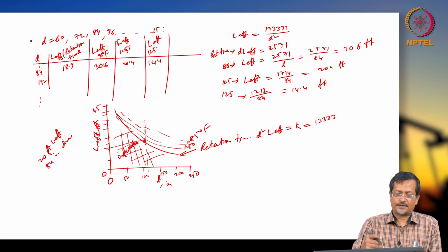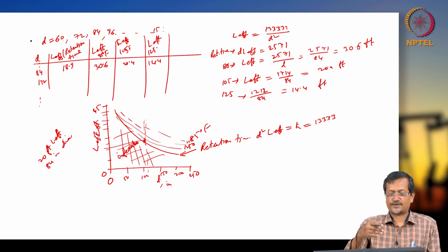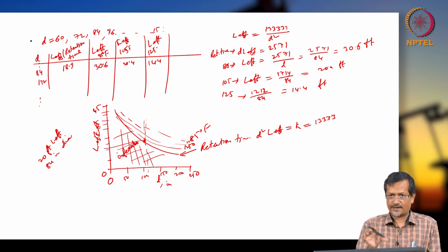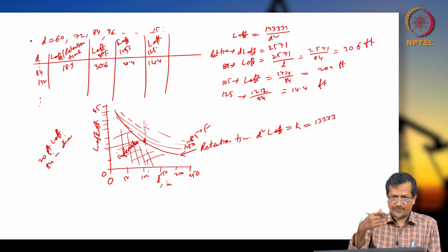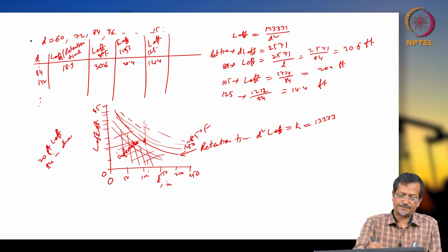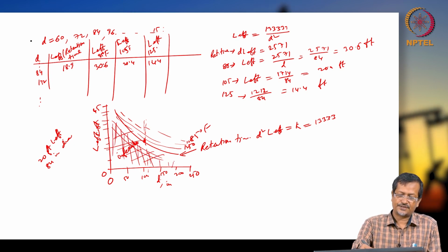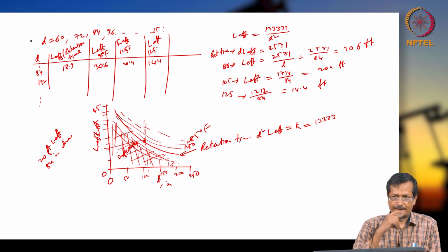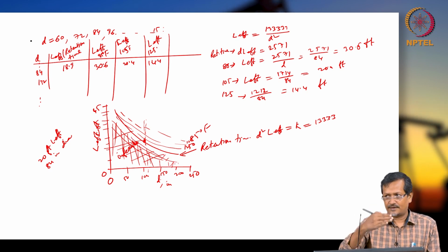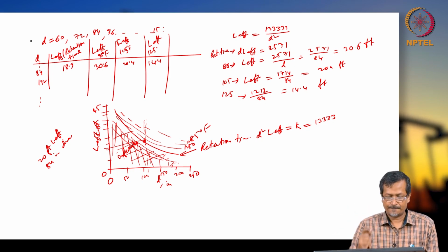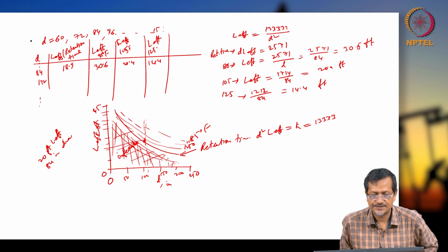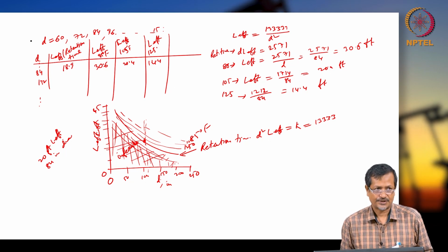Because if you are changing diameter too high, it is possible, but that will not help much. Or if you are going to the infeasible region, this below part, then it will not help. So you have to get the values more than the retention time curve, fine. So this is the calculation for horizontal separator.